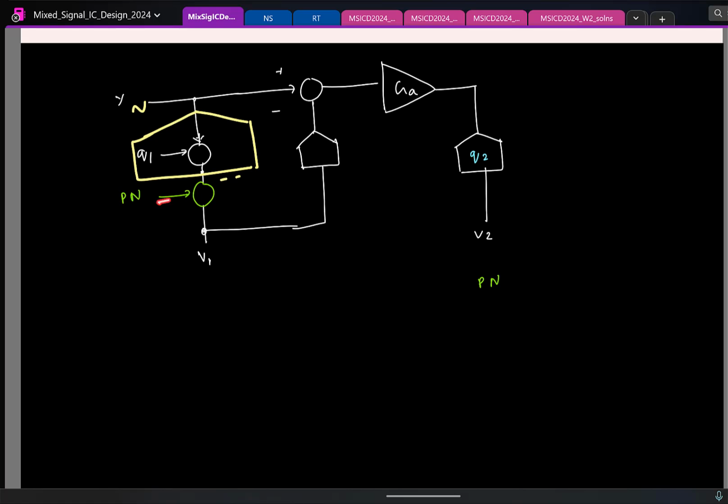So let us say you add it in the digital domain. To start with, let us say the ADC was a 2-bit ADC. So here you would have gotten a 2-bit binary output. So what will be the number of bits you get here? You are adding 0 or 1, so we will basically have 3 bits now. So now the DAC has to be a 3-bit DAC. So that kind of makes the implementation a bit complex.